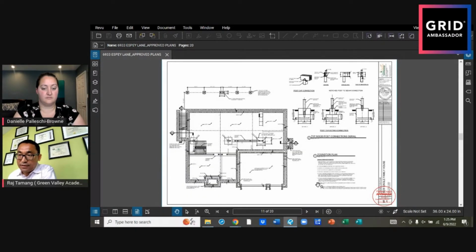The second page is a foundation plan. The foundation plan and the basement plan are almost the same. If you have a slab on grade, it could be the first floor plan because there is no basement or crawl space. Those are all architectural terms, and for that, the foundation part is structural. So it doesn't matter whether it's a full basement, crawl space, or slab on grade, you still need a foundation, right? That's what the foundation plan is. If that makes sense. Yep.